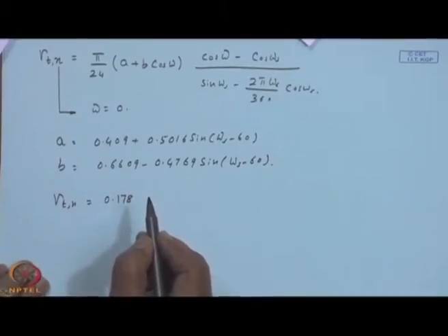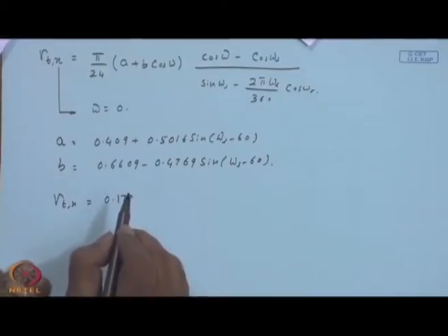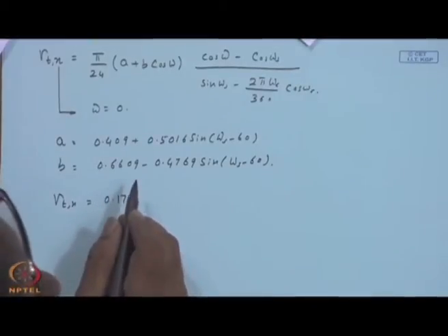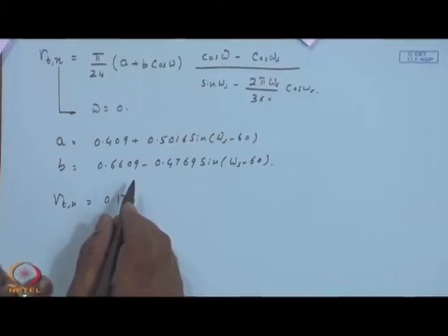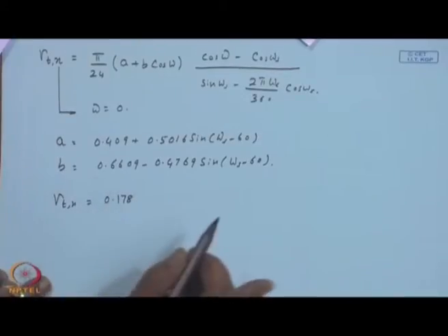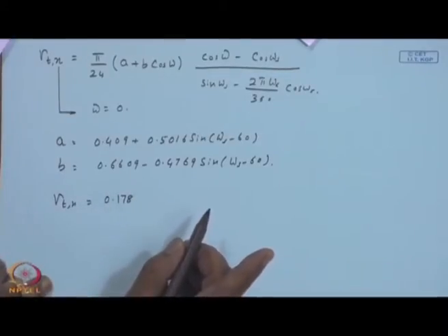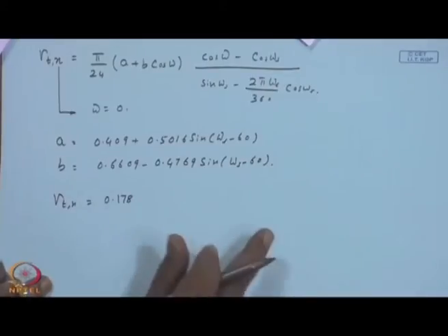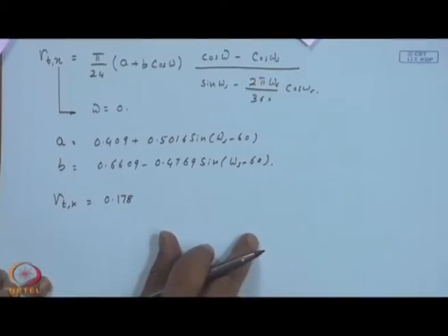Okay. Now, you start developing a feel for the numbers. If your R b factor is higher, the R factor will be less, because that will be multiplied by 1 minus h d by h. So, this is 1.91 for R bar, and R b bar is 2.32. Later on, when we make a similar calculation for summer, then my R b bar and R bar factors will be smaller than what you have got for the winter months.